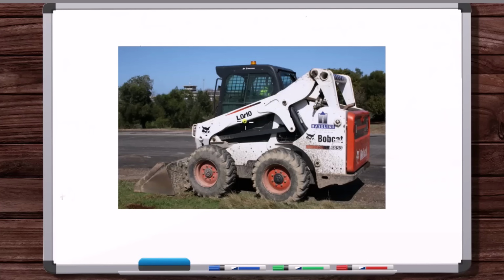And then maybe some of the weight of this beam would be on top of the rubber piece, pulling down on it. So you'd have a surface force on top of this with some portion of the weight of this beam pushing on it. It would be complicated, right? The shape would be weird. It would be some twisted 3D shape. But you could do that and you could solve for the forces.